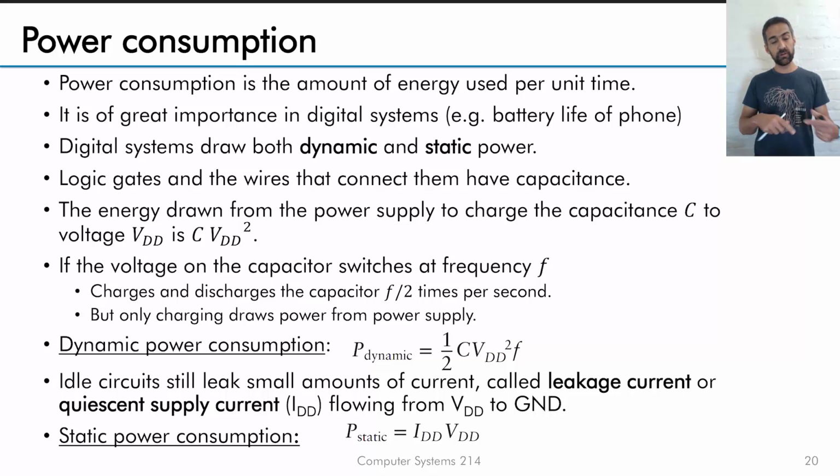So when you do a 0 to a 1 change, it's not a perfect scenario where the output and input have no capacitance and no resistance. It always has a little bit, and especially if you work on a breadboard with those tracks so close together, they basically make a capacitor. So when you have a fast transition as a logical change from 0 to 1 or 1 to 0, that capacitance will have to absorb the current and change its voltage, which means that it will consume power as well.